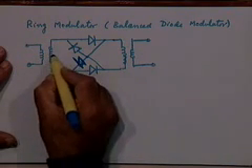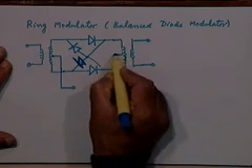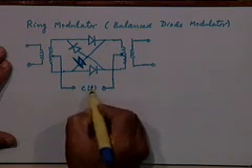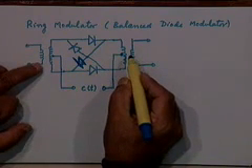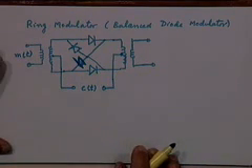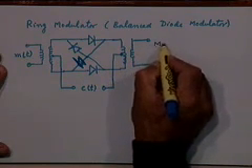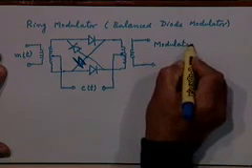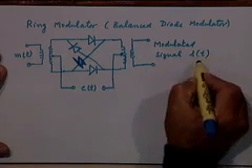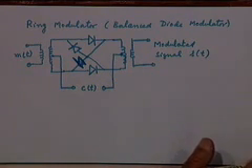So we center tap these transformers here, and apply the carrier voltage C of t at these points, right. And your modulating waveform M of t is applied here. The message waveform M of t is applied here, and this is your output voltage, the modulated signal. Let's call it S of t. The principle is more or less the same.